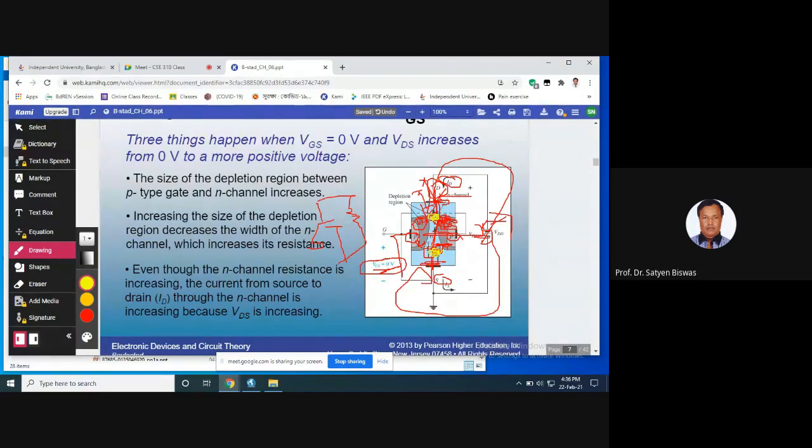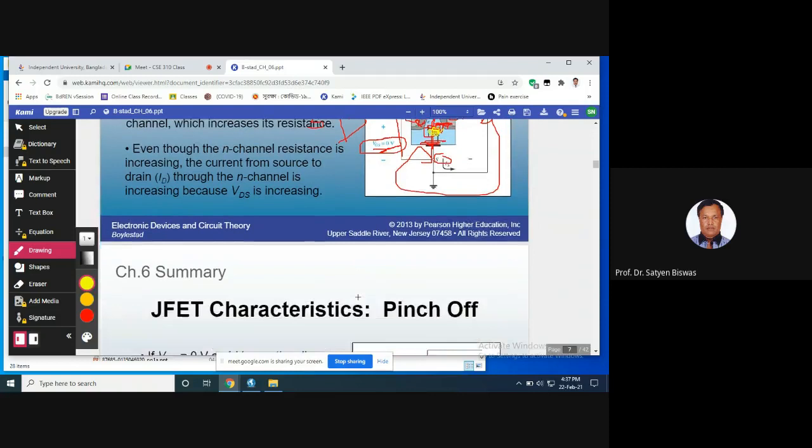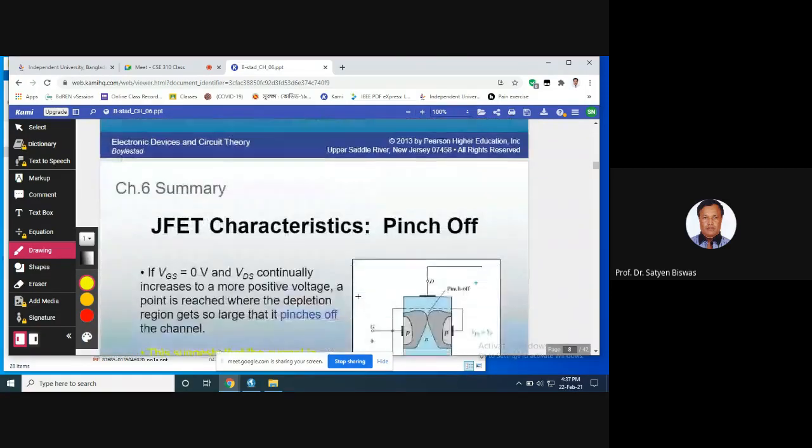So when the voltage is less, that means this is a less reverse bias. Let's say this is 2 volt and there is 4 volt. So with 4 volt, the depletion region is bigger, and here is 2 volt, so the depletion region is less. Understand? So this is the main reason to have these different sizes of the depletion region. Right? Okay, any questions so far?